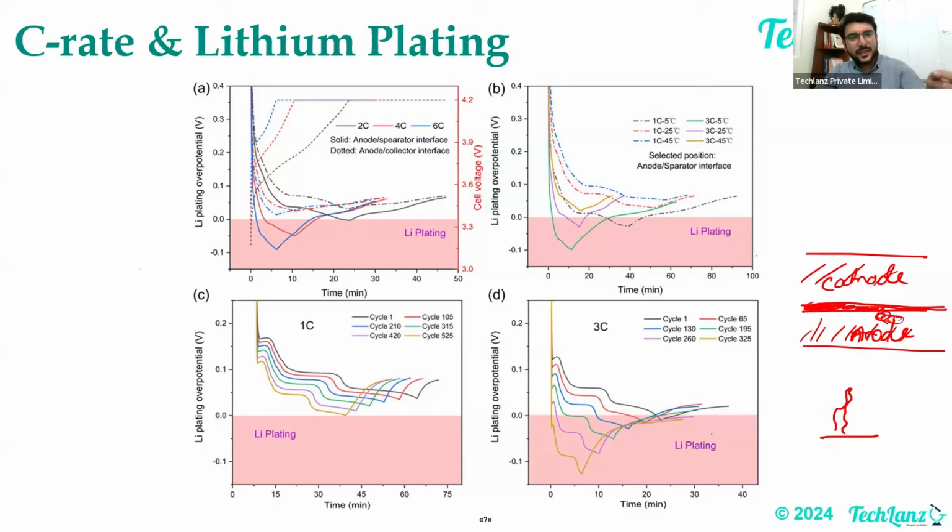Okay, the most typical algorithms being used in the market: one is called CCCV, which is constant current, constant voltage charging. Let me use a pointer again over here. This is constant current, constant voltage charging. CPCV, where you give a constant power and then constant voltage charging. MCCCV, which is constant current in multi-stages. Then there's something called pulse charging. Then there's boost charging, and VCP, variable constant power charging, right? This was what I was trying to tell you in the previous case. Typically, there are two very famous algorithms: CCCV and pulse charging.